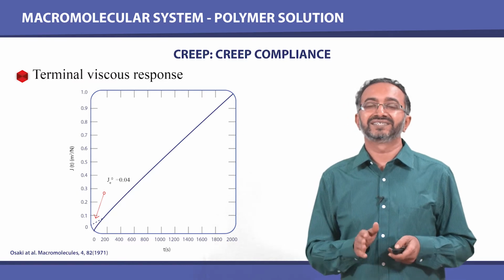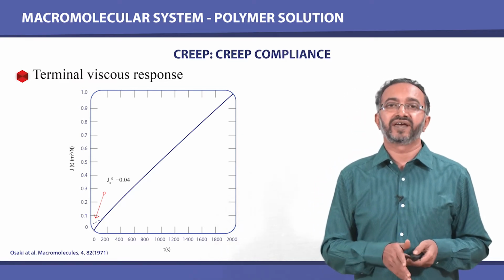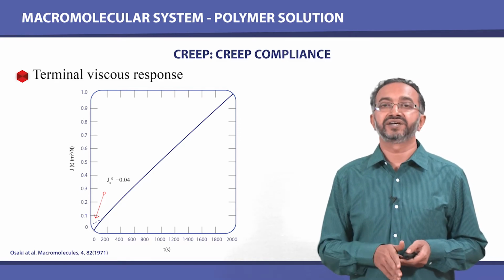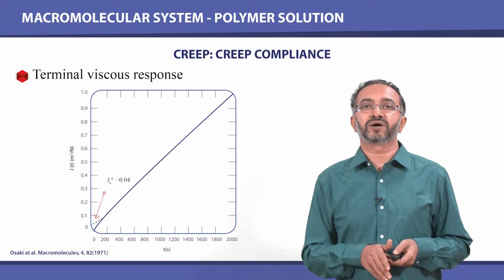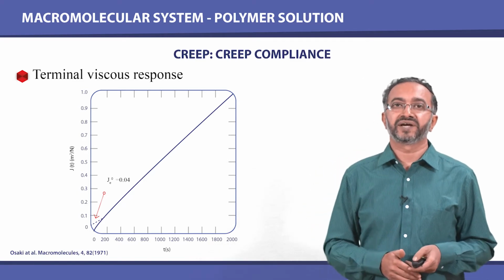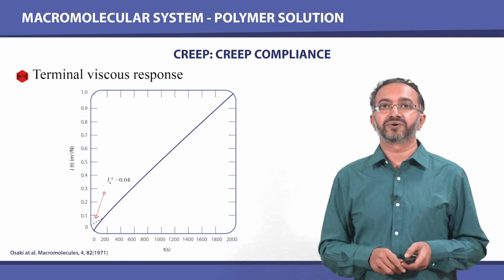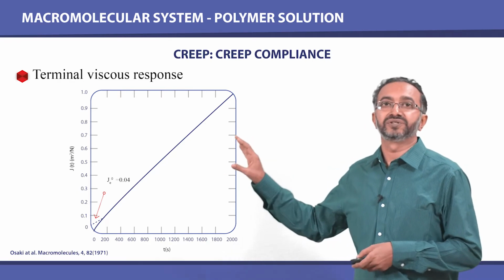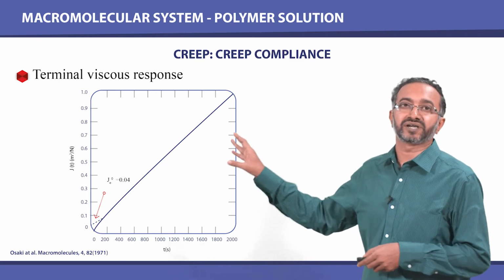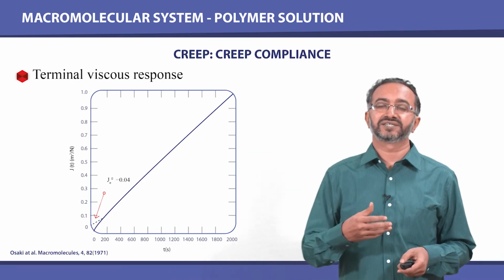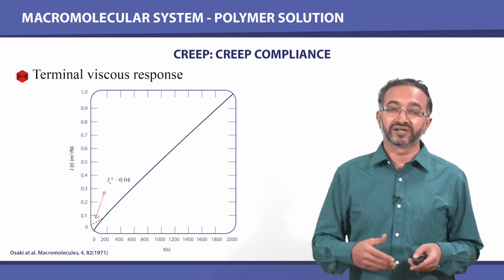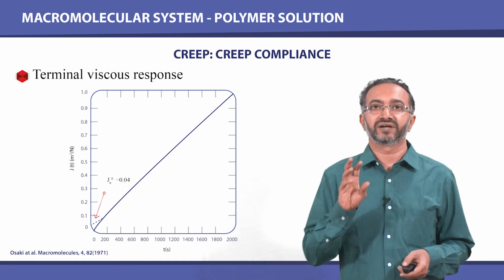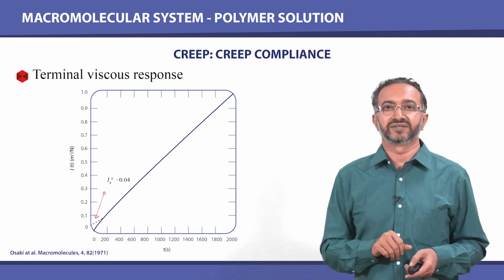And one can see that at very short times, the overall response is not a linear increase in deformation, and therefore creep compliance has a more complicated time dependence, and that is where all the elastic contributions are. By looking closely at how the overall compliance changes at short times, we can get an idea about the relaxation processes in the material, or in other words, we can get an idea about the elasticity of the polymer solutions by focusing on the short time scales.